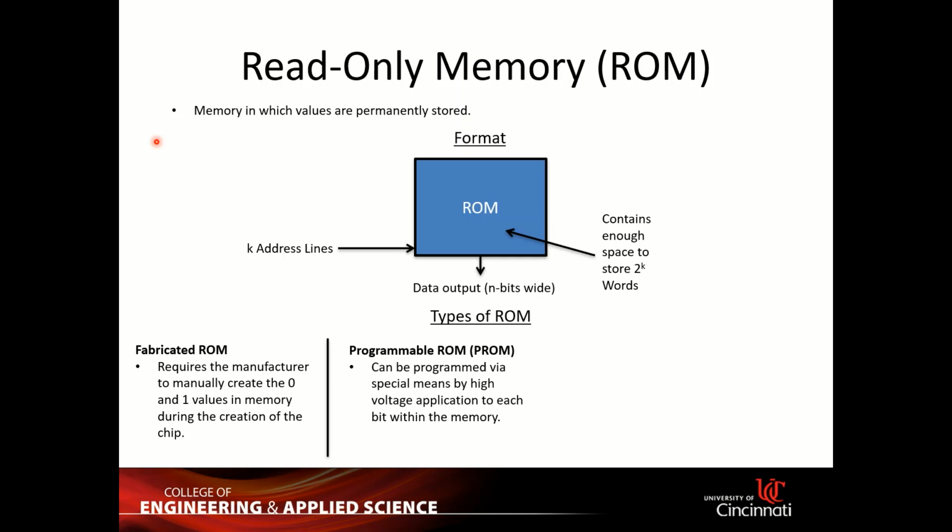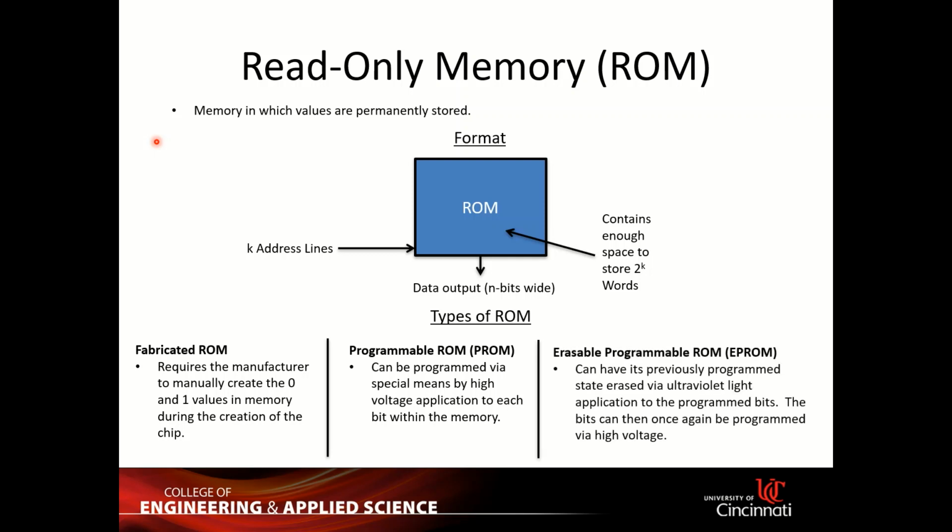Okay, so that's programmable ROM. The last type of ROM is called erasable programmable ROM. So what is the difference in here? So remember, the programming of a PROM is basically a hardware process. You basically blow up fuses to make your program, but the process wasn't reversible, right? It's kind of like an irreversible process.